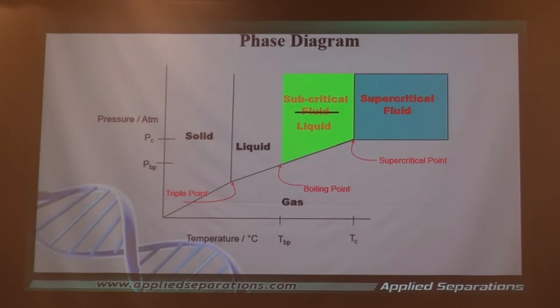For example, as you increase the temperature of the subcritical water, its dielectric constant decreases, so it becomes more and more non-polar. And this gives you some interesting ideas in a halal setting, for example. Now you can do extractions in water that are very similar to doing extractions with ethanol. Again, something for you to think about. And the equipment that uses supercritical carbon dioxide can also be used to do subcritical water work as well. Not supercritical, but subcritical.